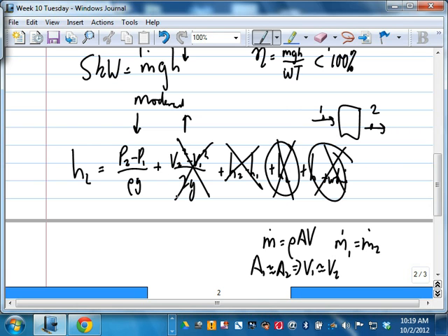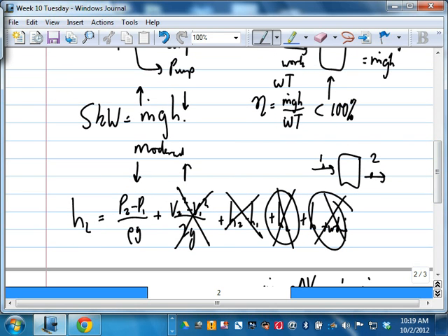If you just analyze the pump alone, what the pump does is put in flow energy. The pressure will rise across the pump. The P2 will be higher than P1. And that's how the pump puts work into the system. Not through elevation, not through velocity change. So the head rise is through the difference in pressure. Okay? So coming back here, since we can, this head pump,